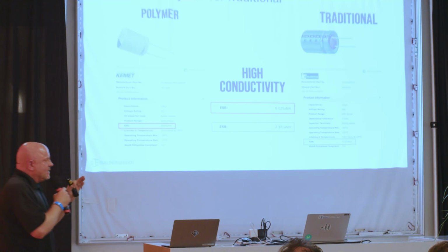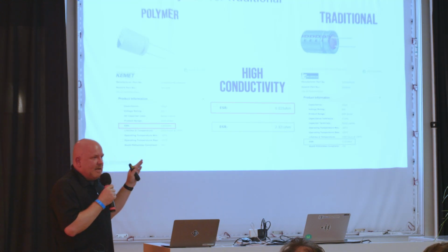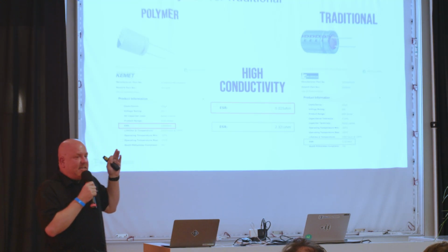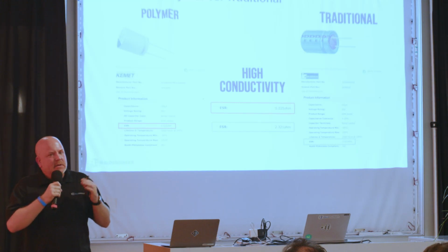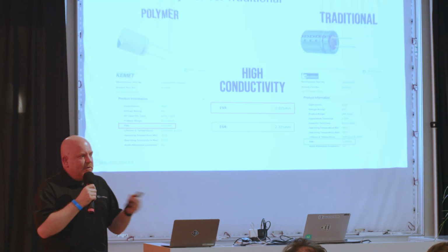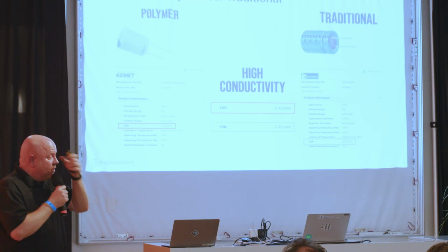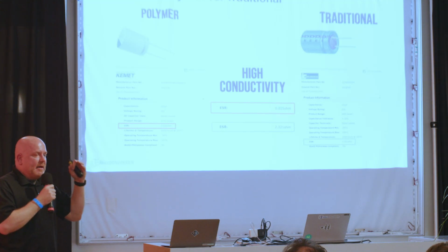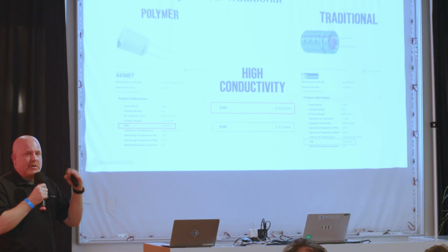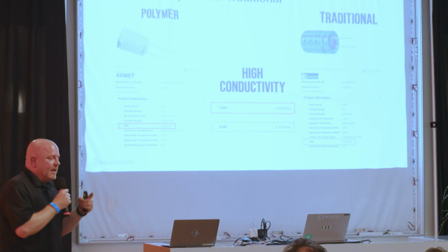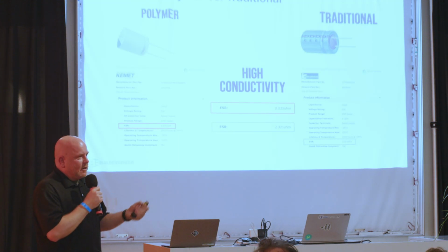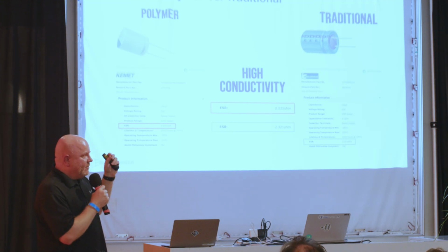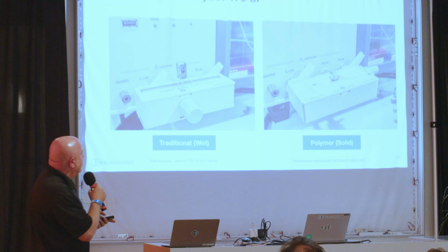The key thing with these is that it's highly conductive, and so it has a significantly lower ESR. ESR is going to generate heat when you run some ripple current through the part. So by using a polymer, you can reduce the amount of self-heating that the part creates. You also get less ripple voltage because it's lower ESR, and you also get wider frequency response.